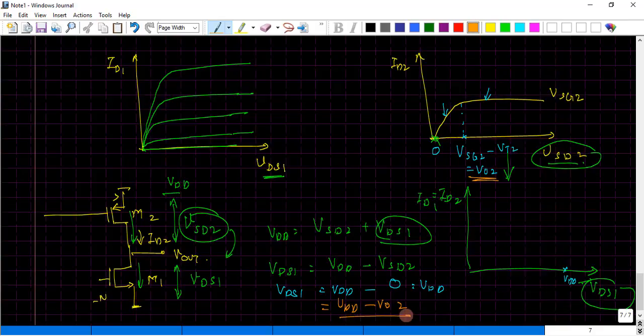And this leads to the new definition of my VDS1 over here. So this point has to be mapped over here. So from VDS and VOV2, and that would point to somewhere over here. So this is the point where I simply mark this point over here. Now, following the same kind of notation, this is the point where my VDS2 has reached my VDD. So when I substitute over here, into this expression, that would lead to the point somewhere closer